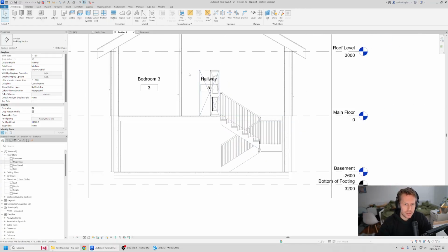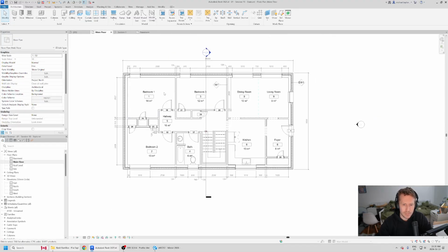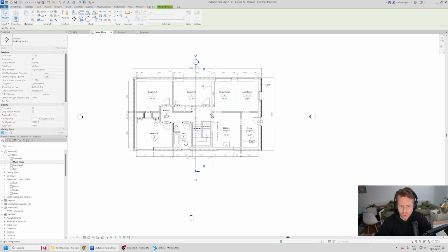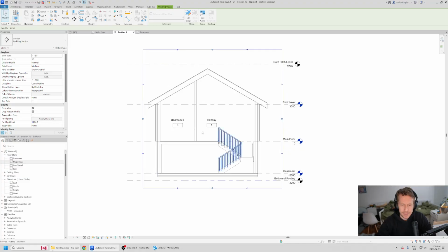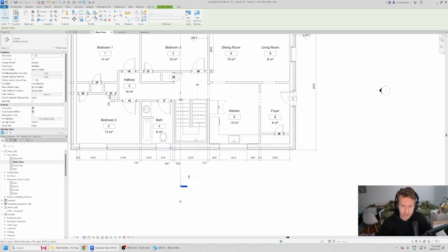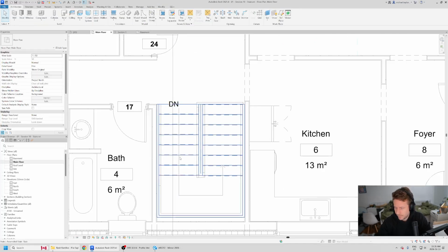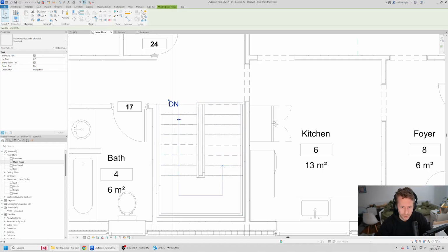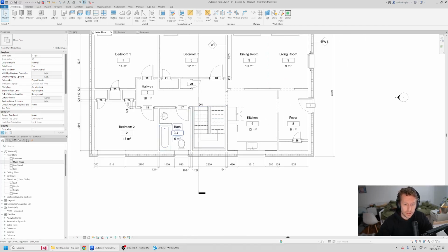One thing that we can do is, you can see I'm looking all the way to the front door here. What I'd like to do is modify that slightly and pull this back so we don't see quite that far. And now in section 1, just clean up that section a touch. And yeah, that's how we generate a nice little stair. So stairs in. You can see here we've got a nice little sketch that says what's down, what's up. So in this case, we could just modify this and move this down up here. Hopefully it looks something like this.